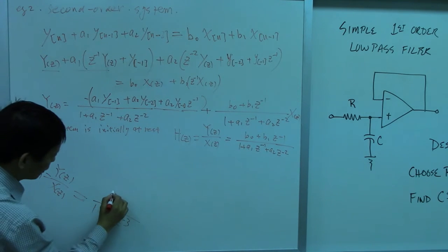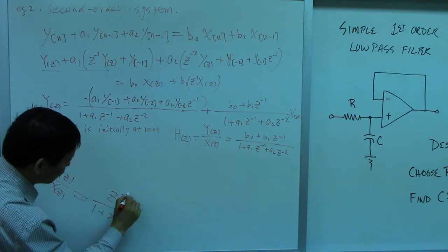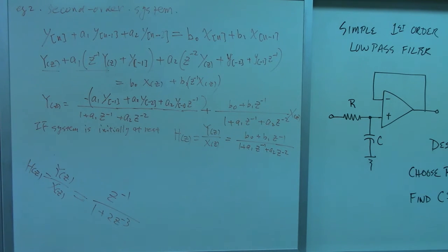If I change this one to z to negative 1, the left hand side is still the same. The right hand side equals what? x[n minus 1]. Make sense? Everybody, are you comfortable with this? You need to be, otherwise you are going to spend a lot of time after the class. We are going to use this a lot of times from today, when we design the systems.